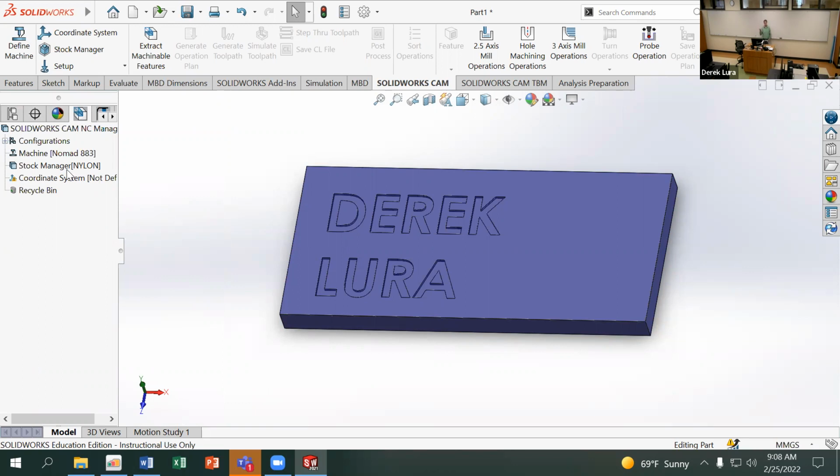And the appropriate material, then that's fine. You don't want the stock to be bigger than what you're cutting out. Keep in mind that if I have stock that's larger than my part, it's going to try and cut that part down to size. So actually having stock that's smaller than your part, if you don't want to cut out the full perimeter of the part, is okay.